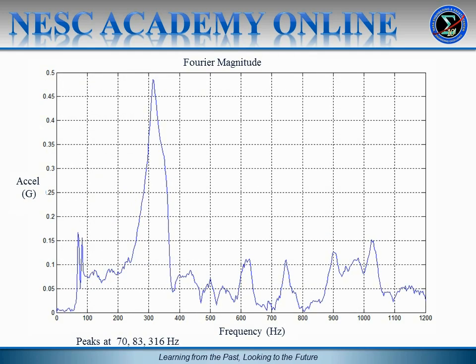So here is the resulting Fourier magnitude for our flight accelerometer data. The x-axis is frequency in Hertz, and the y-axis is acceleration in G. And there are spectral peaks which occur at 70, 83, and 316 Hz. And these frequencies could represent, for example, some structural natural frequencies that were excited by the flight event. And we would need some further consideration to determine if that were so.